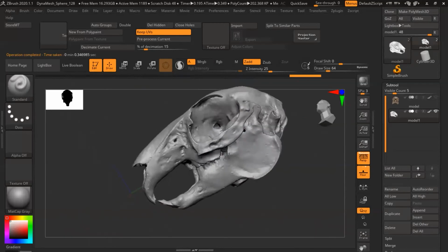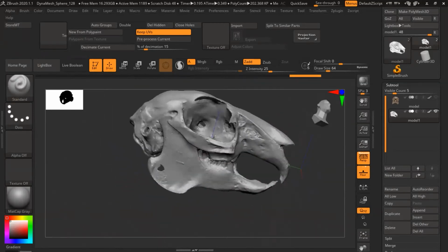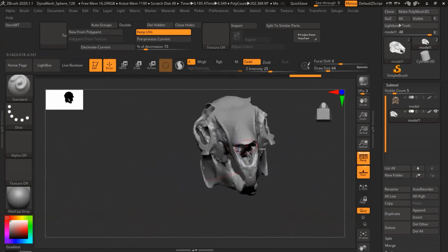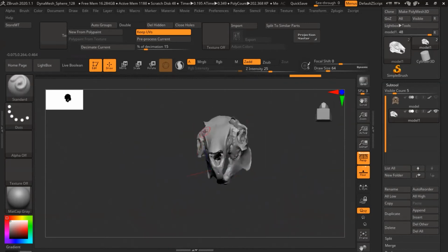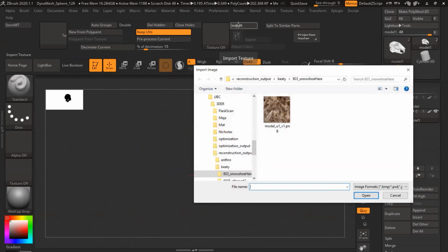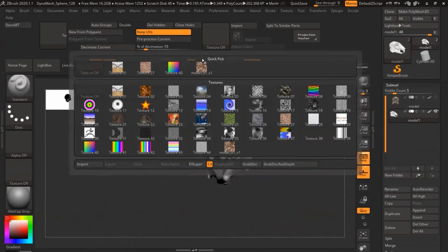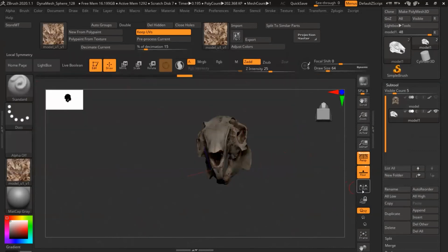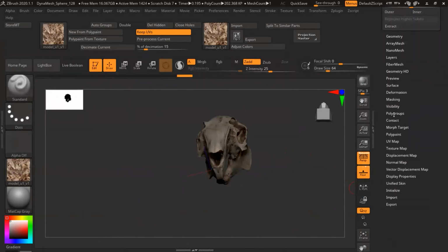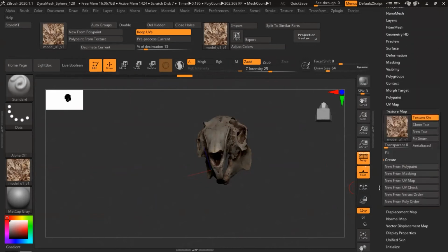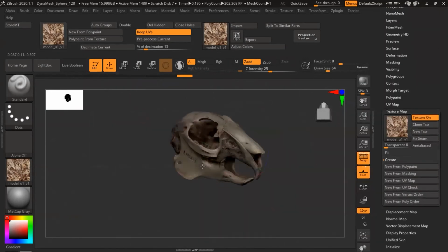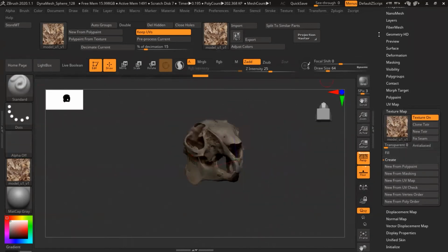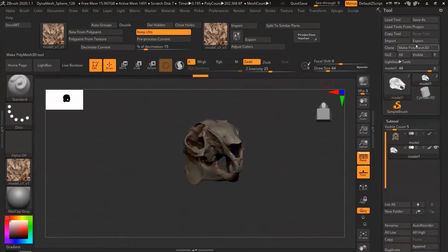I can see that there's not too much model detail that's lost. So that's great. And we lost our texture, so what we're going to do is import our original texture, which is over here. We're going to load it in and check the details. When I put it in, I'm going to flip V, and then load it in and actually apply it to the model. I can do that by going in here, same thing, texture map, and I just selected this. Now I can look at it, and it looks great. Everything is looking great. Now I just need to export it.